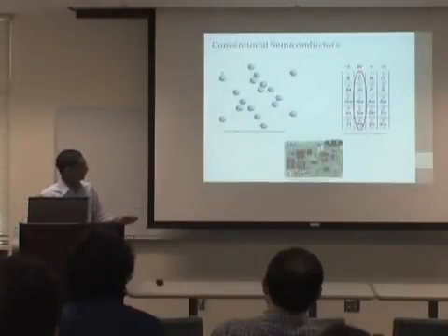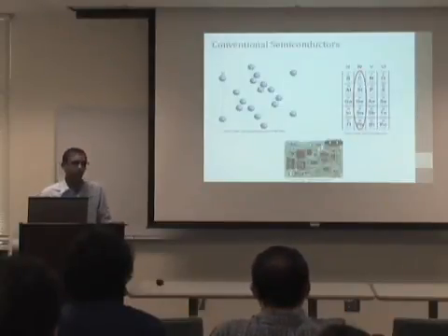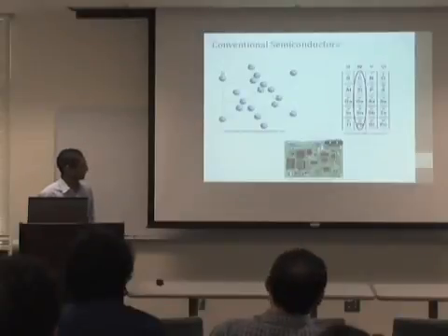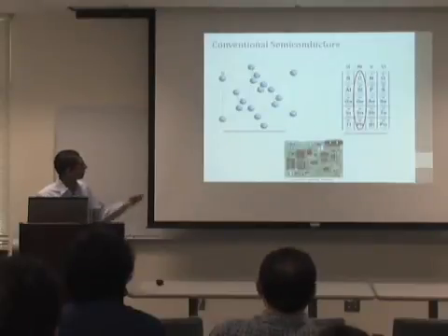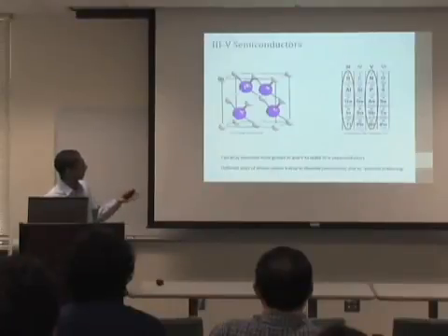So when I say semiconductors, most people think about the elements of group 4, silicon, what you'll find in your motherboards and everything, but it turns out in thermoelectrics, it's actually beneficial to have more than one size of atom in your crystal structure. So if you're looking at your group 4s, you have one size of atom. It turns out you can make semiconductors by alloying group 3 and group 5 elements. So here's indium phosphide, just a general 3-5 crystal structure.